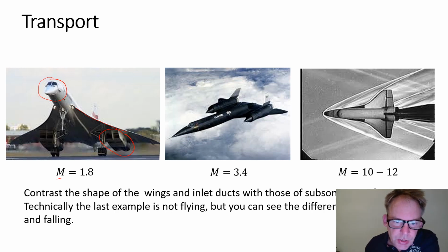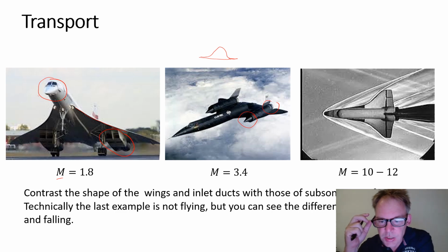What you'll see here is that it's got, again, a flared cross-section, sharp edges, and you'll see this cone at the inlet. There's an afterburner here, and what we'll discuss later on is why the geometry has that particular shape and why that shape changes as the Mach number increases. The challenge of running a craft at subsonic and supersonic, because obviously it has to start off at subsonic speed, is that what is designed to run efficiently at high Mach number is a disastrous design feature at subsonic flows. So you need to be clever with your design, and that's what they overcame.